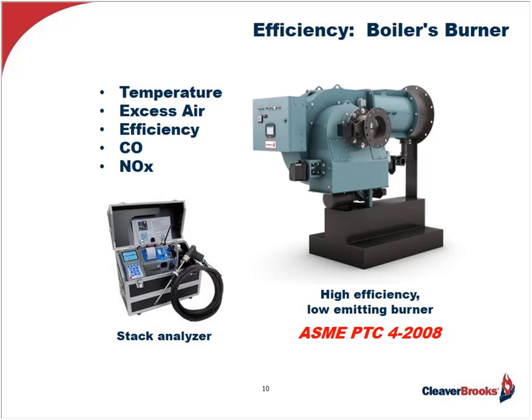Now, I said begins with this analysis because it will get you close to the actual efficiency. But to really determine the actual efficiency of this boiler, it requires a closer look and a procedure as outlined in ASME PTC 4-2000 will take the variables into account, going beyond just the stack loss. Things like steam and feed water flow, moisture in the stack gas, so it would be moisture losses, and clocking of the fuel meter for actual input will provide the true indication. These factors will provide the true indication of how much of the fuel burn is actually going into the boiler water to make steam.